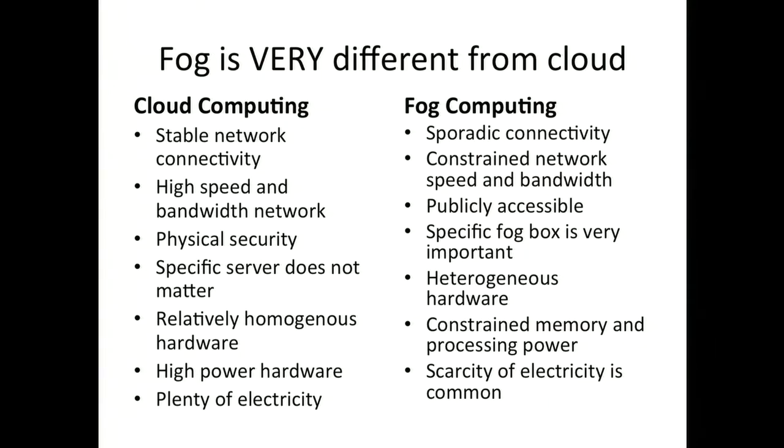You've got an ARM 64-bit, and then an ARM 32-bit, and then you've got an x86 Intel Atom processor, and so on, and you're trying to mix all these things together. And they don't tend to have a lot of memory, and they don't tend to have a lot of processing power. They're decent, but it's nothing like you'd put in a data center. And sometimes you have to be very mindful of wireless transmission, because they don't have big enough batteries and they're going to run out of juice. So you say, I can get my data once an hour, and you would need your software to be aware of that.